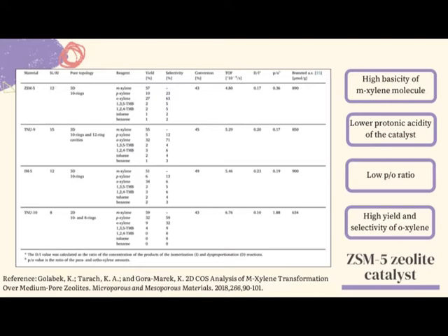The PO value is the ratio of p-xylene to o-xylene amount presented in the product mixture. Hence, the lower the PO ratio value, the higher the amount of o-xylene production compared to p-xylene. As shown in the table, the diffusion of o-xylene molecules in zeolite TNU10 channels is strongly inhibited and the highest p-xylene selectivity is observed. However, in zeolite ZSM5 and TNU9, o-xylene has higher yield and selectivity compared to p-xylene. Further research found that the structures of TNU9 and IM5 deliver a serious constraint for o-xylene molecule diffusion and its further conversion.